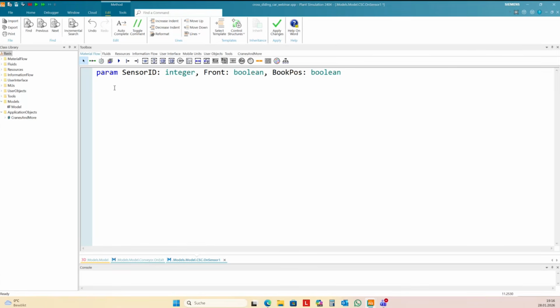First, I need to stop the part. And then I move the complete conveyor. And the conveyor here is a question mark underline 3D. This is all the 3D methods and attributes, and the method I need is blade translation.